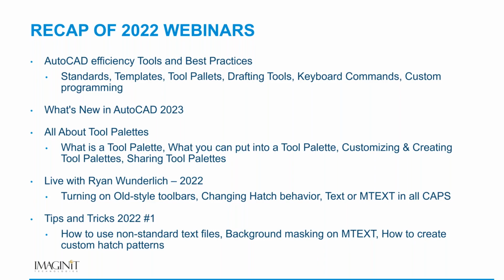I did a live with Ryan Wunderlich 2022. This was turning on old style toolbars. This was changing hatch behavior. And this was text and mtext in all caps. And then the last one I did was a tips and tricks 2022 #1, where I talked about how to use non-standard text files, in other words, how to use SHXs correctly, how to do background masking on mtext, and how to create custom hatch patterns.